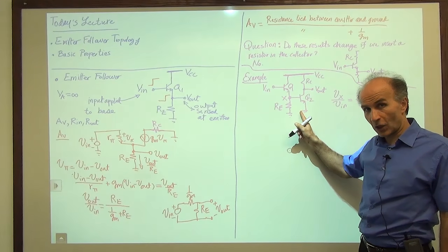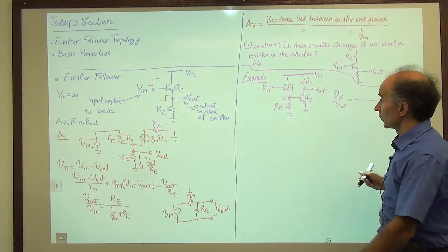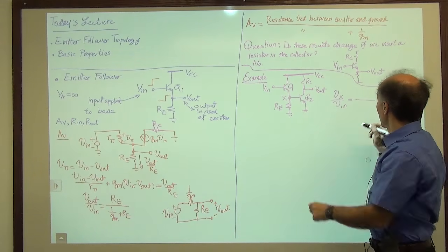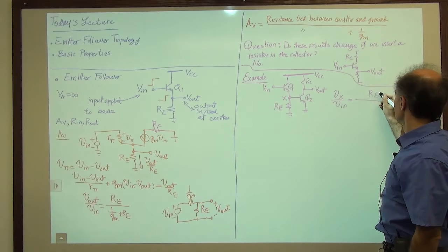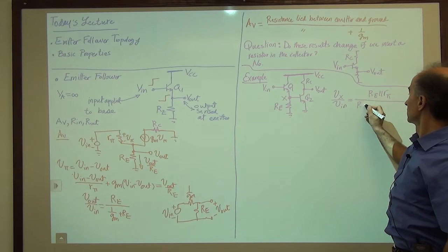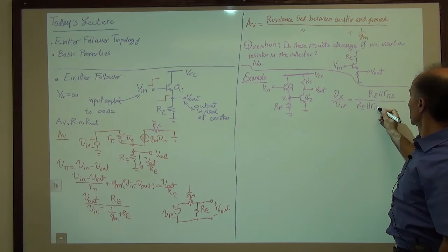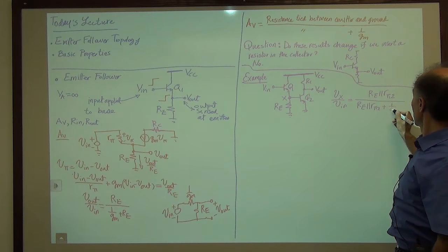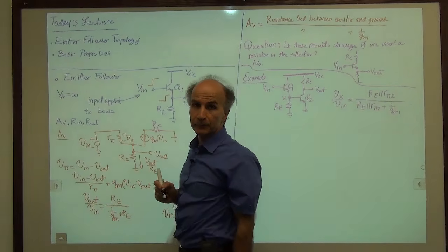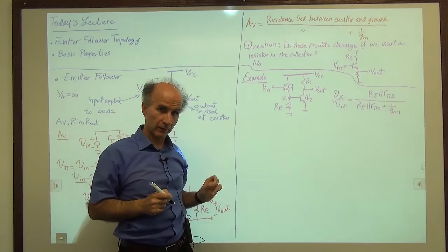The input resistance of a common emitter stage with no degeneration is r pi. So what we really have from X to ground consists of RE in parallel with r pi, and that's what should go up here. And again down here, and to make sure we don't get confused, this is r pi 2, and then plus 1 over gm1 as stipulated by that term over there. So this is the voltage gain from the base of the emitter follower to its emitter, and it's less than 1.